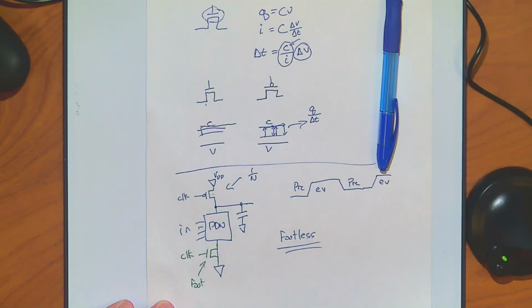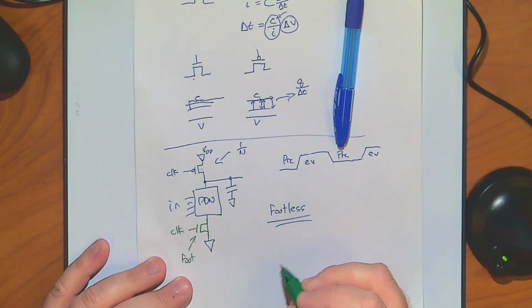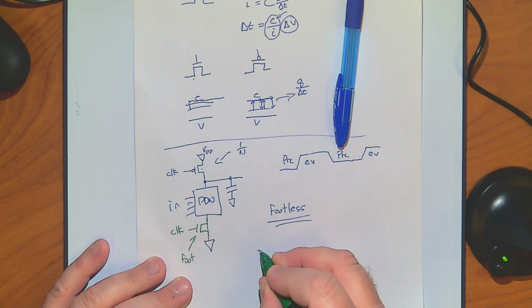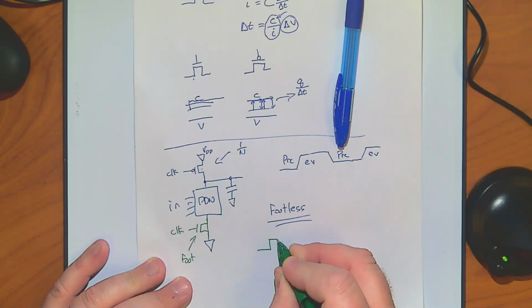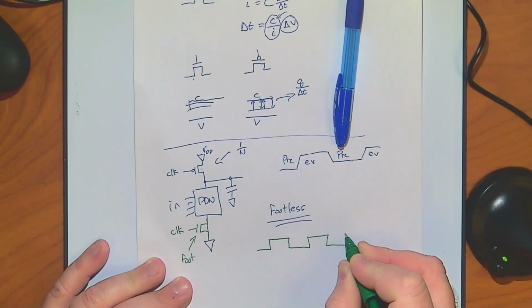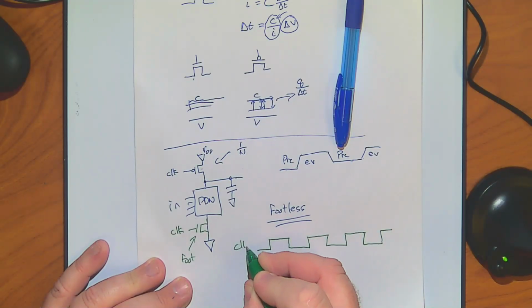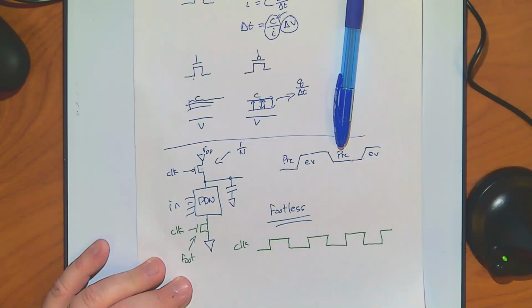So we've got this basic sequence here. Let's think about how it works, because this is kind of our key idea. We've got this series of a pre-charge stage and an evaluate stage. So imagine I have this timing diagram that's going on. This is my clock. And you build your pull-down network just like you did before. You make your Karnaugh map. Basically, anytime you want to drop those zeros in, you make sure this pulls it to ground.